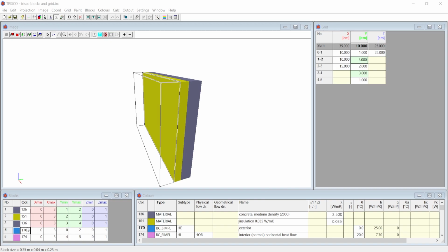To do this, first, select the block you want to move. To select the block, click on the select icon on the toolbar at the top. You can click on the same icon to deselect the block. An easier way would be to directly click on the index number of the block to select it. Now, if we want to move this block below the first block, click on the first block, choose Move Selection after, and notice the block has moved on top below the first block.